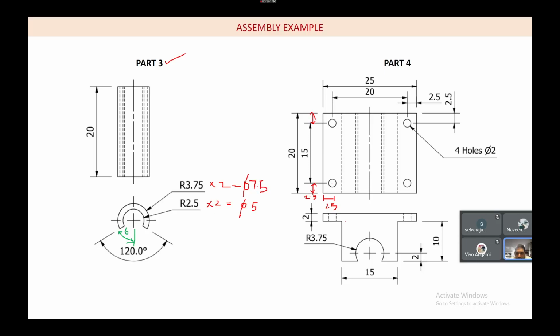Yes. Now we have to select this angle, this one. Okay. Now 0, we give 60, it's coming this way. So if I give 120, now you can see that if you satisfy this 120, it is now sitting perfectly. So 120 degree, I click apply. So if I now check the DOF analysis, it is now fully constrained.